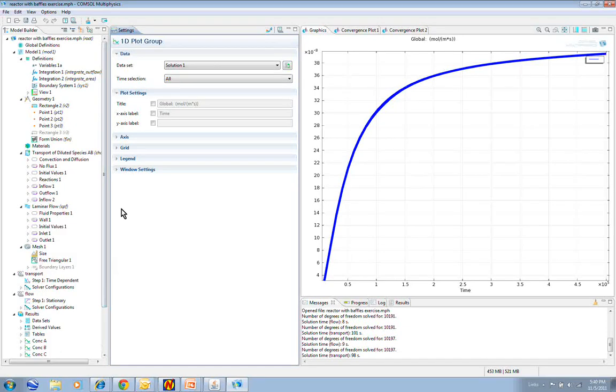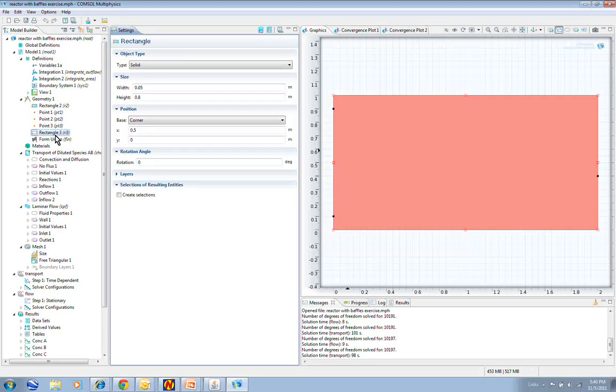So what I want you to do is set this problem up like I've set it up here, and then see if you can adjust the design of the reactor to get a better mass rate out. Here's what I tried. I said, well, let me put in a rectangular baffle. I set it up already, and it looks like that. That will be a wall, and we'll have the flow go around that wall.